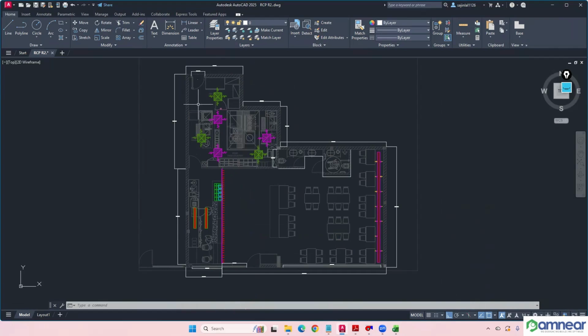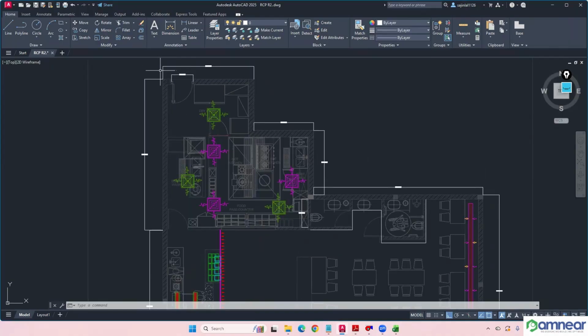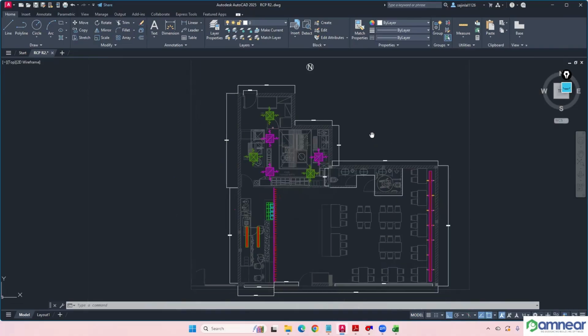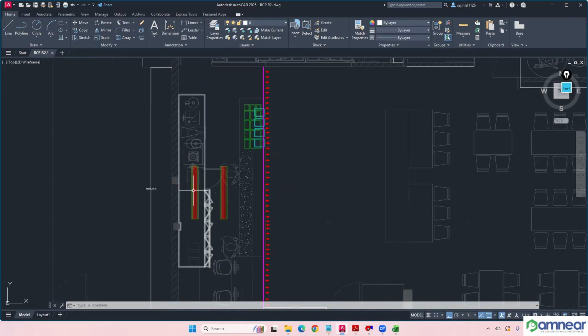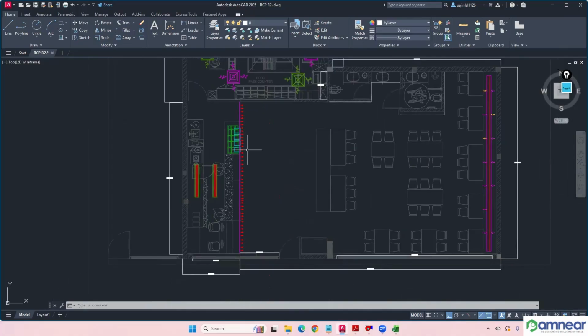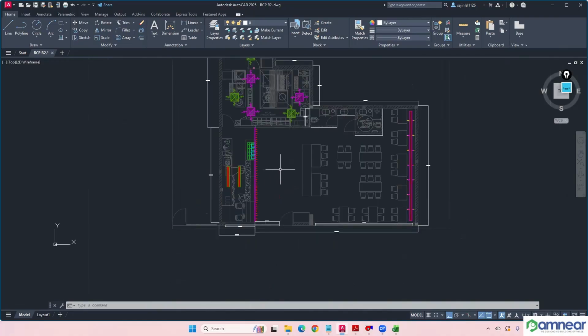And after the discussion with the architect and the possible location we have proposed, and these are the 8 terminals we are having. For example, within hot kitchen area, we are having square diffusers, 3 supply diffusers and 3 return diffusers are there. But the next size we have to select. And in the front areas, like serving area, we are having like linear slot diffusers only, 1 supply and 1 return. And side throw is there, side throw grill we have to propose there.